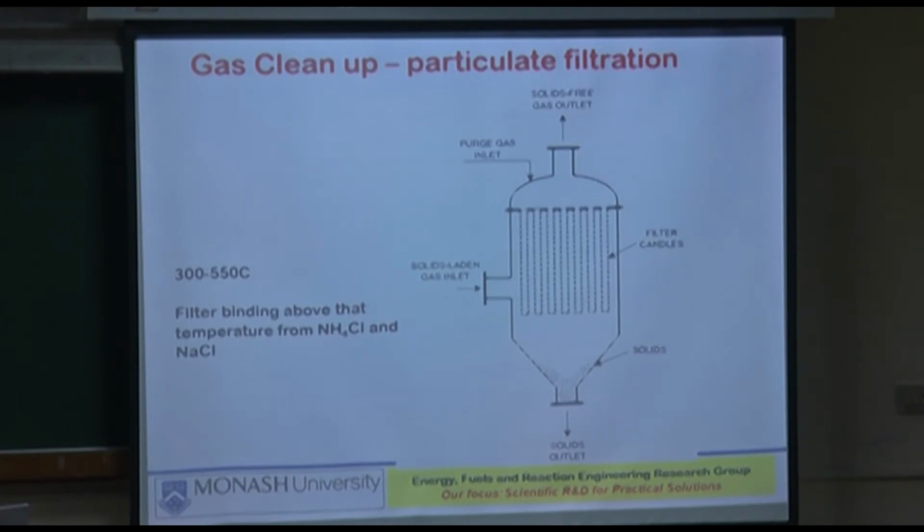So if you are purging for 2-3 minutes, then for those 2-3 minutes syngas quality is decreasing, right? Because it's all high pressure nitrogen. So it has to be kept very low. So that's the important bit.